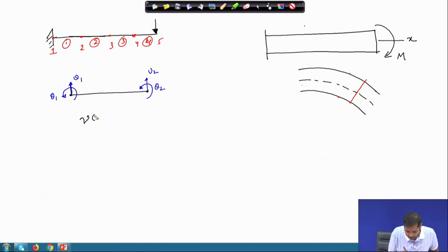So, V(x) gives you the transverse displacement at any point. Okay. Now, then what will be the slope? Slope at any point, theta, will be dV/dx. Okay, dV(x)/dx, that will be the slope. Now, this transverse displacement will be same for this point and this point. But what happens to the longitudinal displacement? You see, at the neutral axis your longitudinal displacement is 0, if the longitudinal displacement say is u.